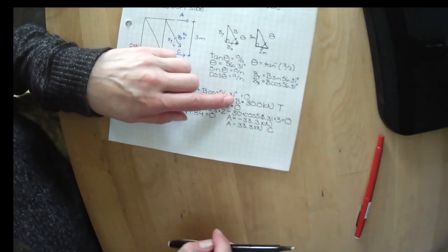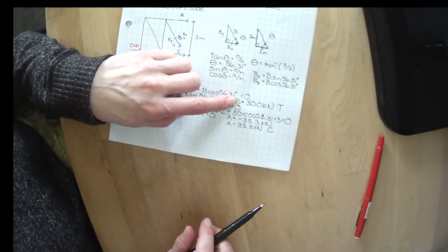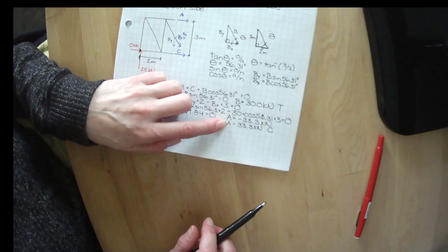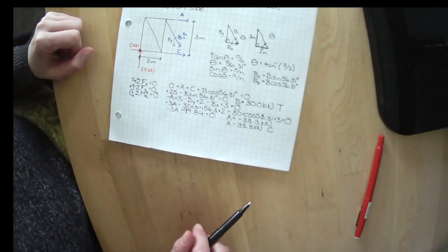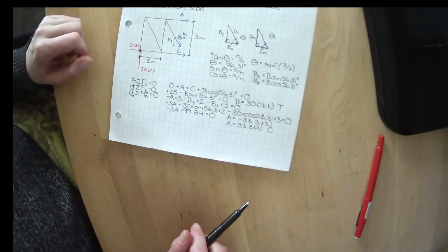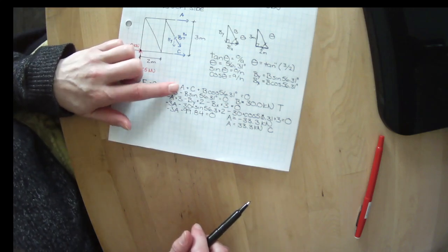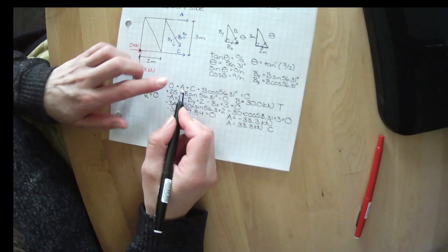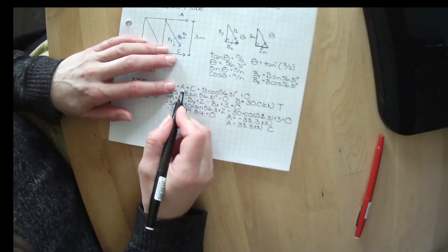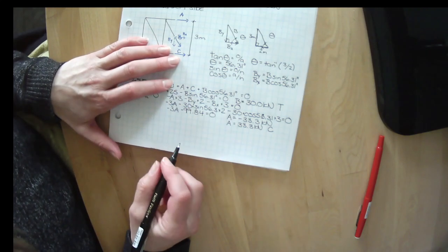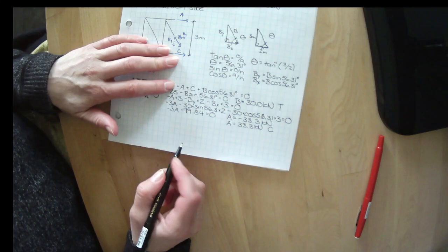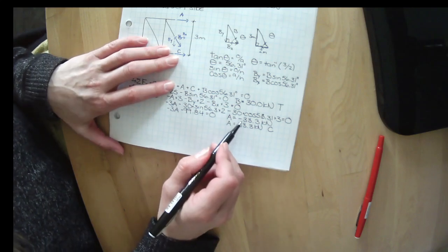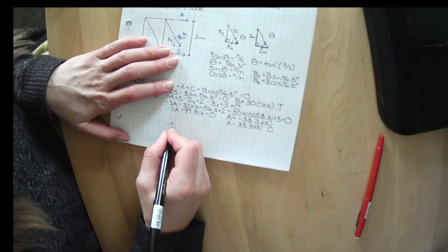So we know that B equals 30 kilonewtons in tension, and that A equals 33.3 kilonewtons in compression, but we still don't know what C equals. So we can come up here and plug these things back into this. In this, I was still drawing A in the positive direction, and I know it's now minus 33.3.